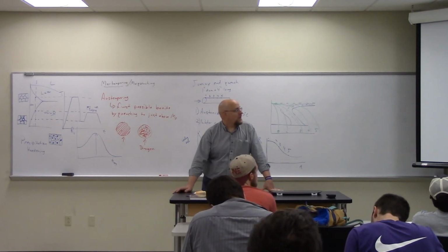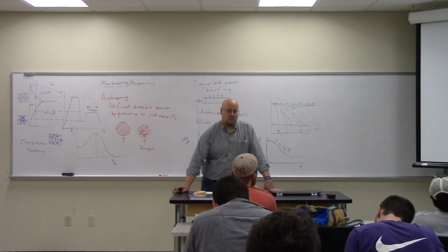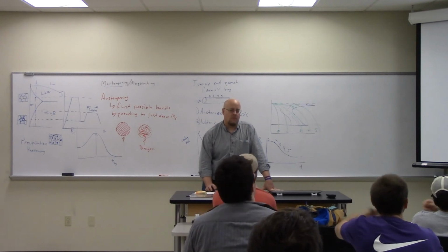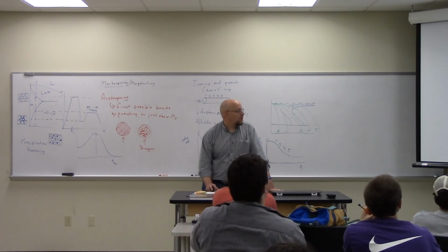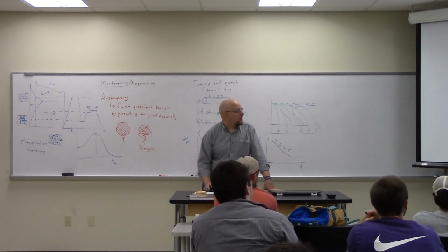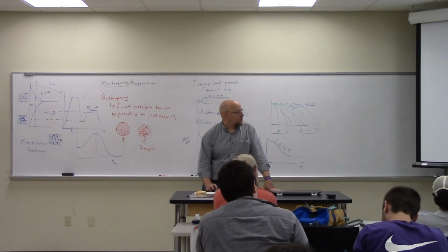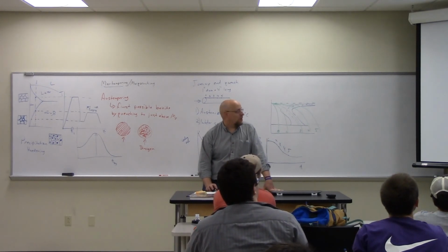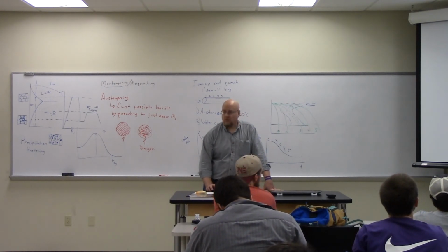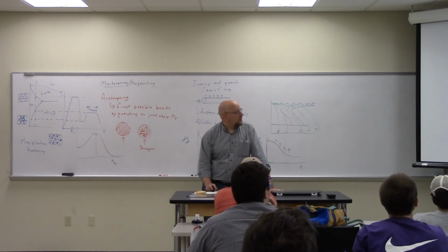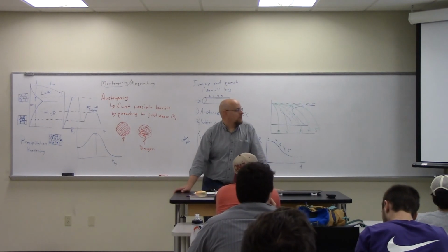Okay, now let's repeat it for E. For a cooling rate of exactly 1 second. What do you think is going to happen? We're going to miss the knee. Right? It actually starts off here to the left, because notice this is a log scale, so this is 0.1 seconds. So in the first tenth of a second, it already dropped from 727 down to 670. Okay. So we completely missed the knee.